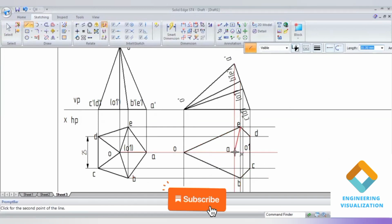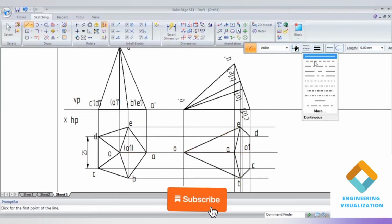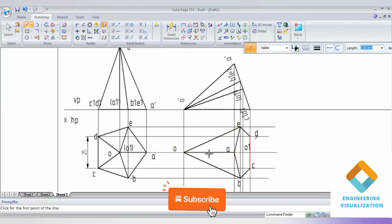From the top face, the pentagon is visible, so it is continuous, and A dash 2 is also continuous, AO. But the triangular faces DO and CO are not visible, so they are drawn with dashed lines. And the axis we have to show.